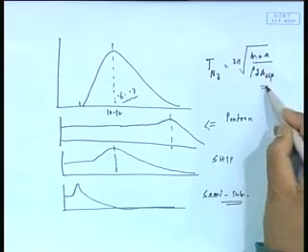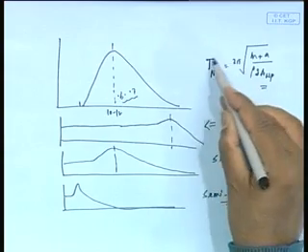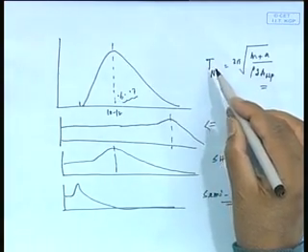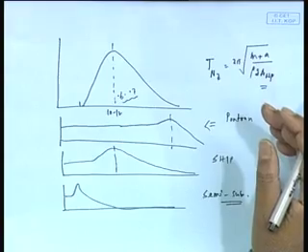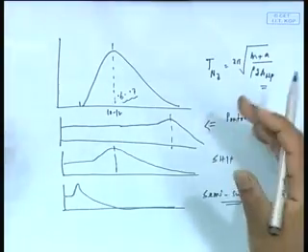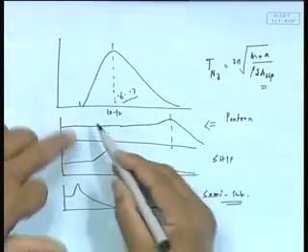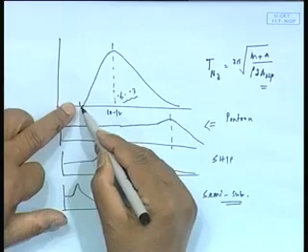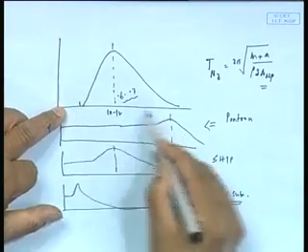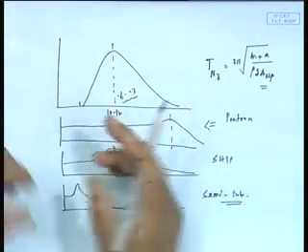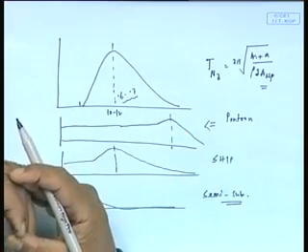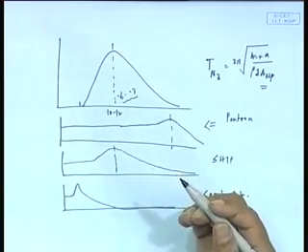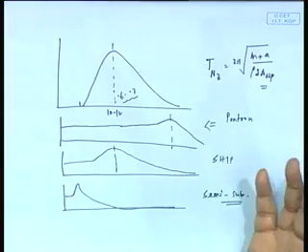That is exactly why you of course lower this AWP to make sure TN is actually about 20-25 seconds, and if you did yesterday's calculation, you will find out that around that, even at a very high sea state, there is practically no energy. Even if you go high, this side is actually lower than 20 seconds or so. So, if I have a structure with a 22 second, 25 second natural period, this peak I am going to have very low response. This is the full idea.